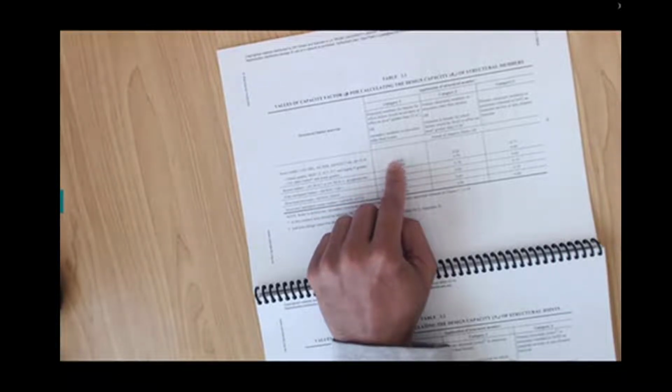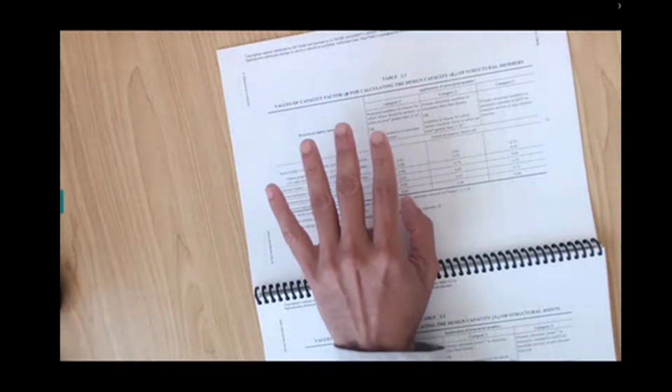So in that case, they are just recognizing that your penalty is low, because you have 5 to 10% penalties that the standard wants to recognize. That is okay. Then you come to category 2, which is considering more safety, meaning that this is a primary member. If that member fails, you have a reduction of up to 15% to 30% penalty applied to your design. So in category 2, where you are designing the primary members and that member fails, more than 25 square meters of area will be affected.